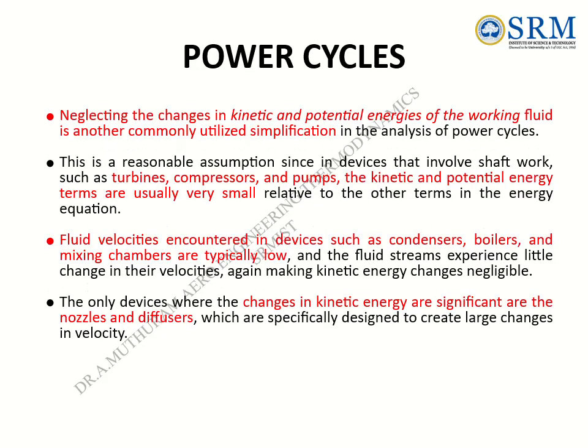Neglecting the changes in kinetic and potential energies of the working fluid is another commonly utilized simplification in the analysis of power cycles. This is a reasonable assumption since in devices that involve shaft work, such as turbines, compressors, and pumps, the kinetic and potential energy terms are usually very small relative to the other terms in the energy equation.